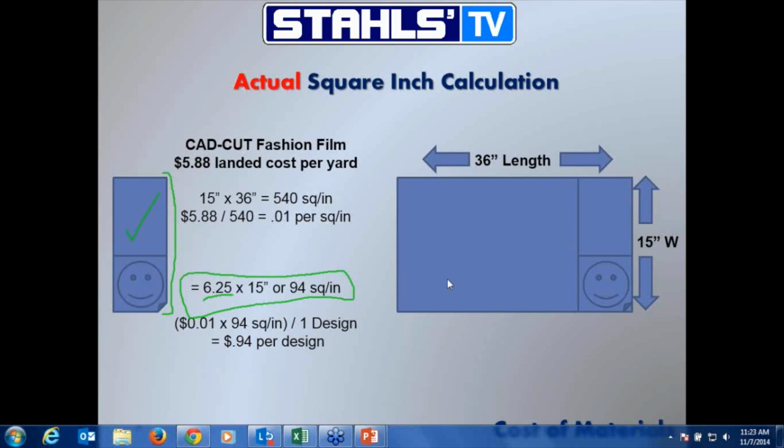Now you may say, like I would, it would be just as cost effective to cut 2 designs out of that material at the time of getting the job. So how about offering the customer an additional discount on 2 shirts, or setting a minimum quantity of 2 so I can do a better job nesting and utilizing material? Or how about offering the customer a sleeve print or a back shoulder print or something that I can at least nest up and leverage this material so I can add more money to the selling price without increasing my cost. I'm just using what would be in the scrap drawer anyways. So work to efficiently utilize your material.